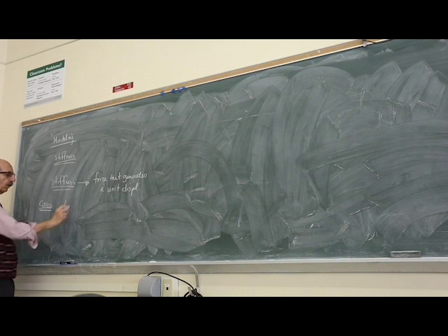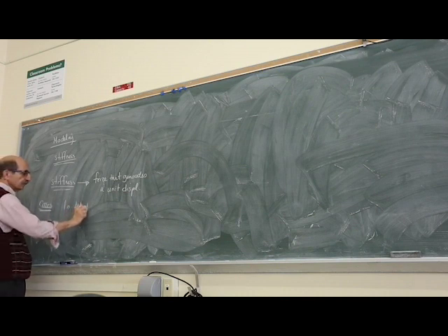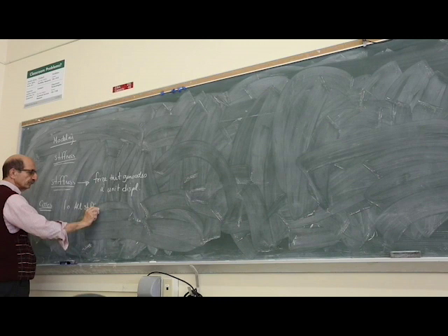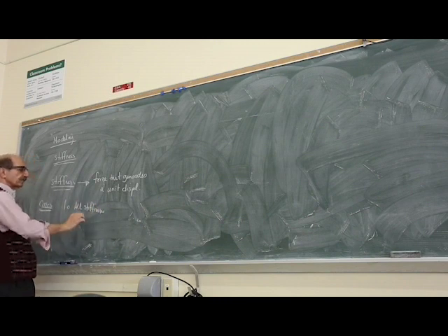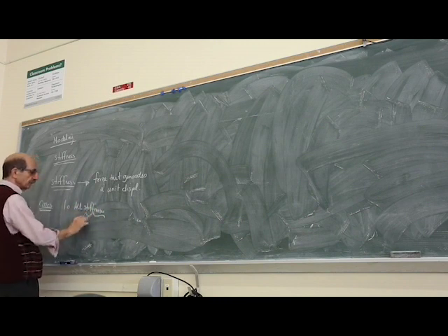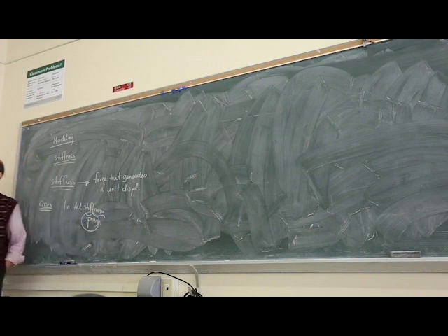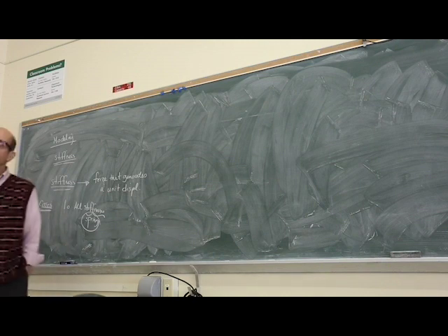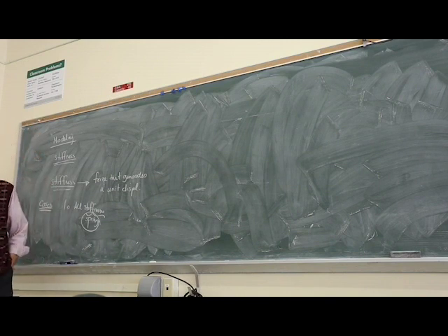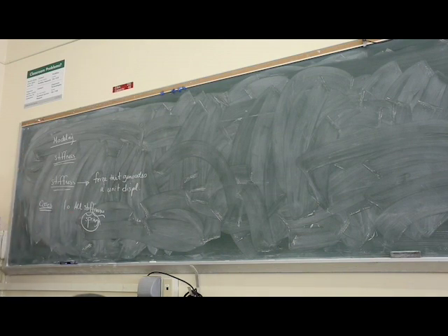Either all the stiffnesses, and as you can see, I emphasize stiffness elements, we call them springs, because we are dealing with only one directional motion. In other words, in vibration, we are assuming that each of those elements experiences just either an axial deformation or rotational deformation, but just one deformation or one degree of freedom.